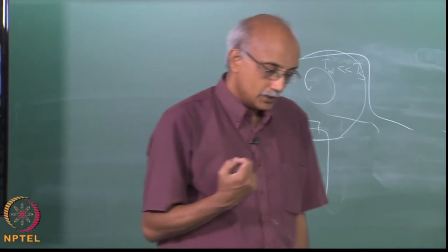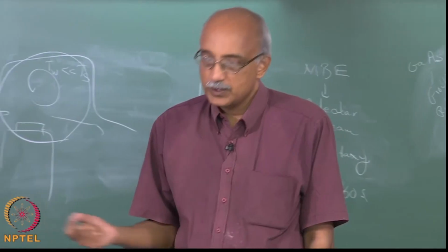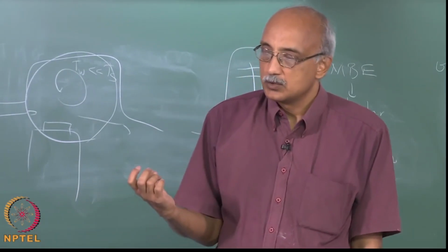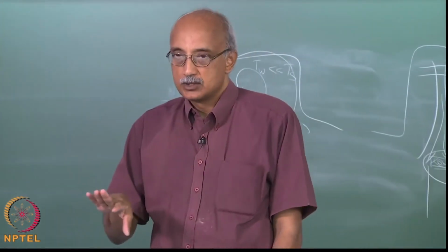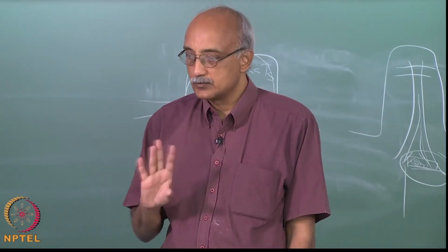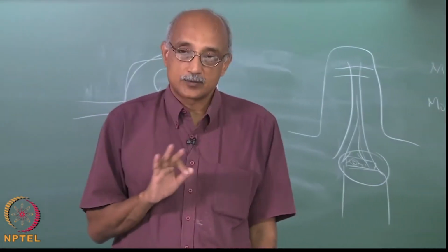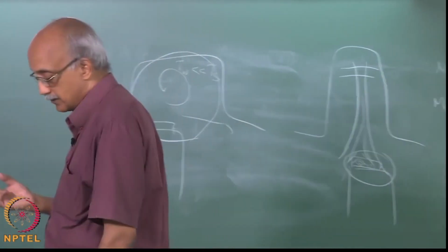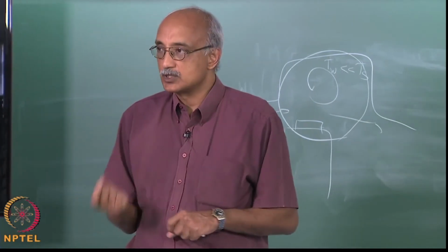is that typically adhesion is being achieved by chemical interlocking. You are relying upon the species that wind up on the substrate to chemically react with the surface and form a film. Now, in principle, chemisorption forces are much stronger than physisorption forces. However, that only applies when you can guarantee chemisorption to happen.